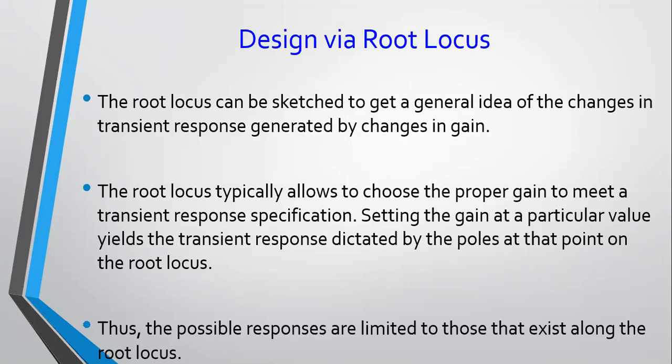And remember, we covered all these topics in the chapter on second order systems, where we looked at parameters for transient response like the rise time, the settling time, the peak time, percentage overshoot, damping ratio, and natural frequency. All these things we've seen are related to the location of poles in the complex plane. We'll do a small recap of that in a later slide.